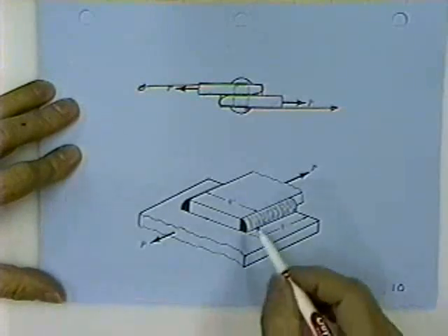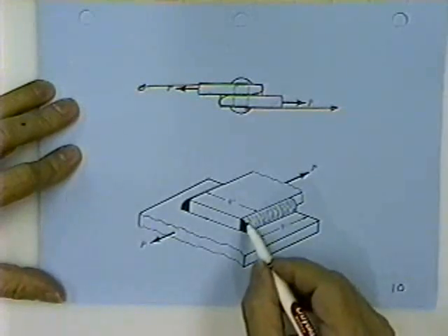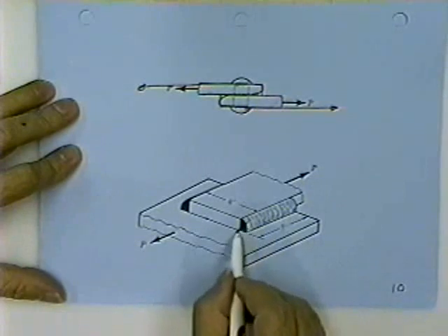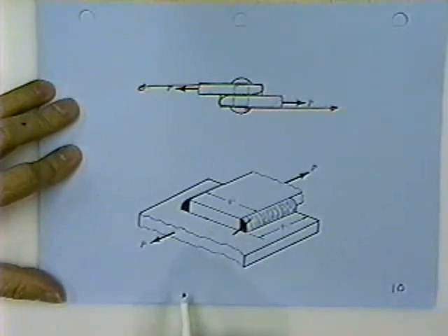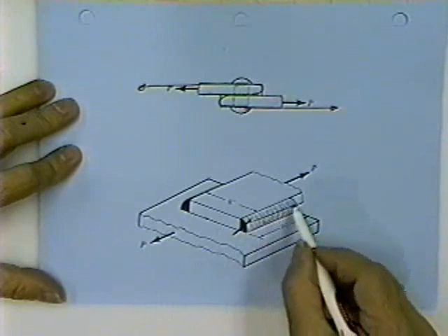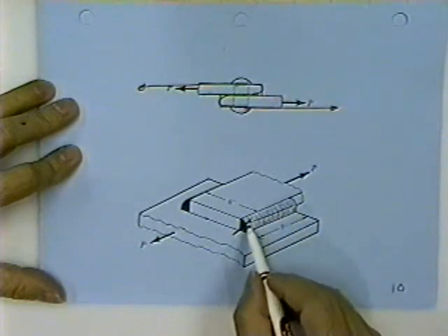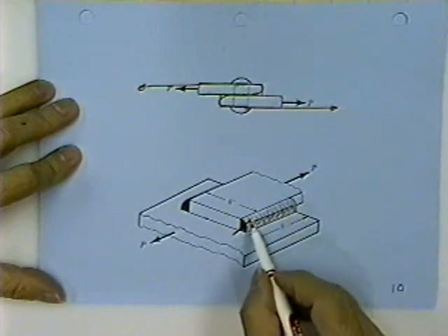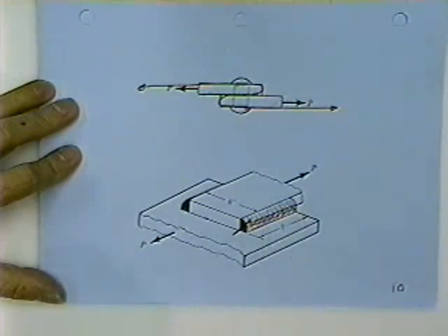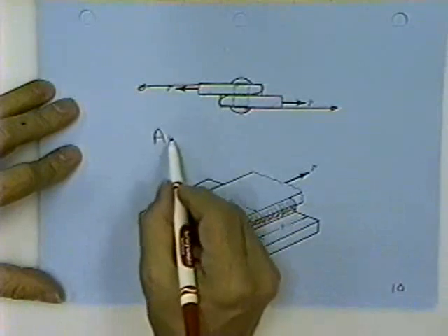Now then, a weld works pretty much the same way. The shortest distance this weld could fail is right across what's known as the throat of the weld. It's at a 45-degree angle, dead between the vertical side of the weld and the horizontal side of the weld. And the surface area that would fail would be right along that throat. You could kind of cross-hatch it down in there. If the thing was made of glass instead of steel, I could even show it to you.